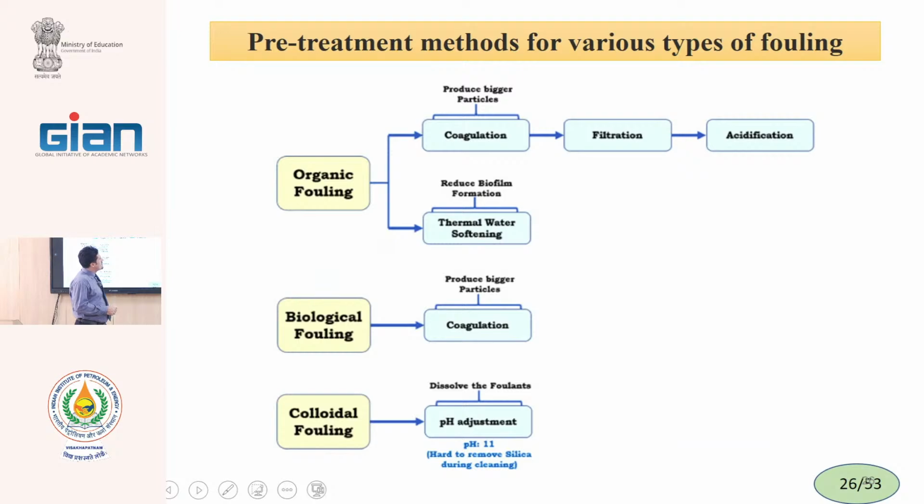For organic fouling reduction, we must remove the organic agent. The most used process is coagulation with addition of aluminum and iron salts to water and use of calcium hydroxide, some precipitation is produced and adsorbs the organic matter and removes it from the water.